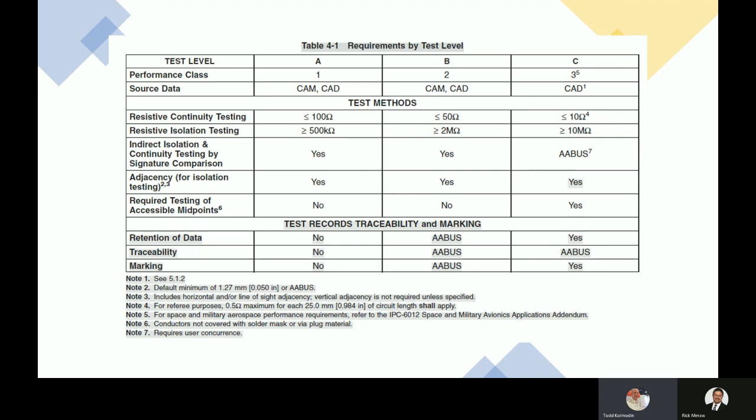Thanks, Rick. One thing I want to stress is to make sure you read the fab drawing and find those notes in there. And if it doesn't look right to you, definitely question it, because some of this product has been around for a long time, and they've spun the revs a few times. An engineer back in 1982 might have written some notes in there, and he retired, and then they spun the product and just started cutting and pasting notes from revision to revision.